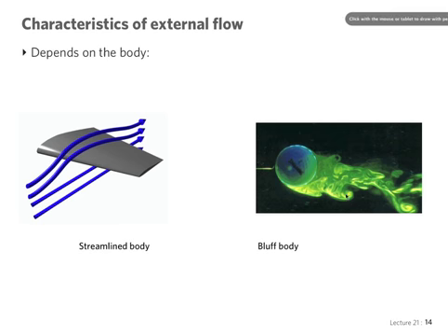So we have here the wake, and the wake is generally a very disordered flow with concentrations of eddies of different sizes that interact, very unsteady flow. And this characteristic of bluff bodies is what we call separation. So we'll discuss this a little bit more. For example, a cylinder, a ball, all of these objects are bluff bodies.